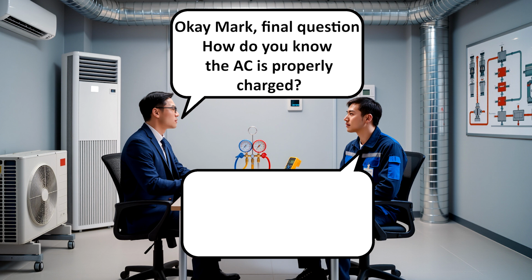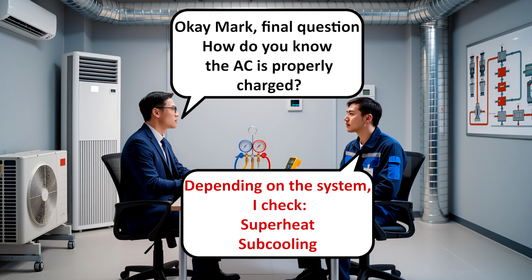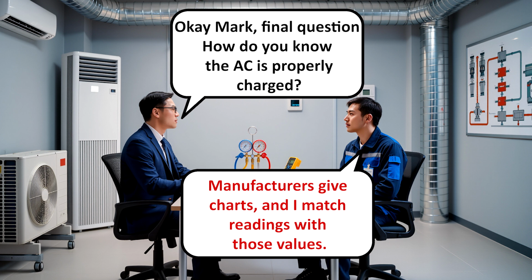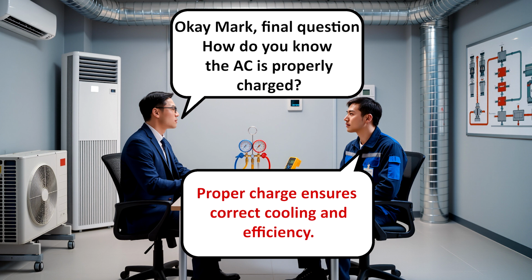Okay, Mark, final question. How do you know the AC is properly charged? Depending on the system, I check superheat, subcooling, suction and discharge pressures, temperature split across the evaporator. Manufacturers give charts, and I match readings with those values. Proper charge ensures correct cooling and efficiency.